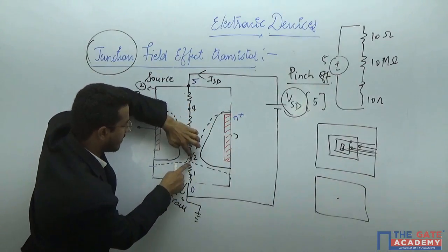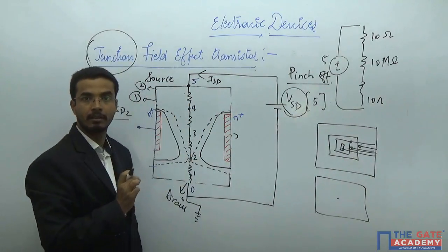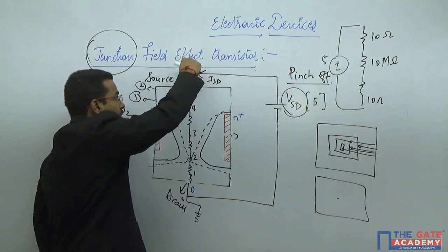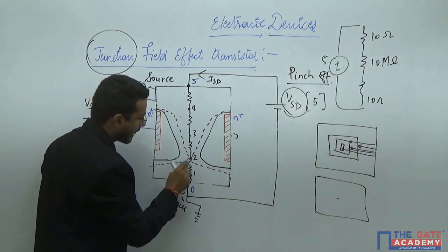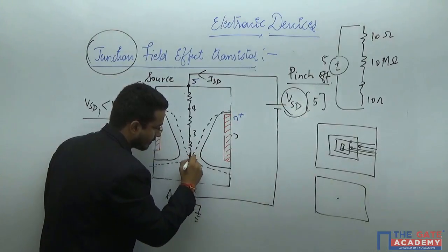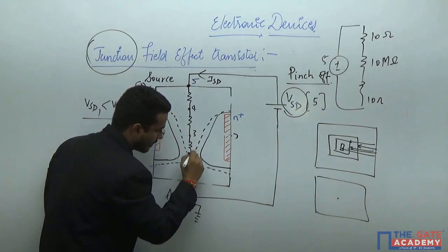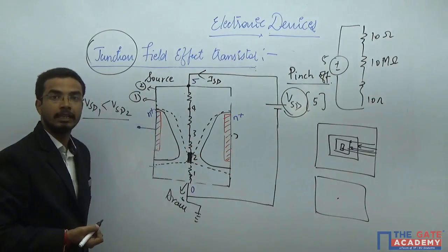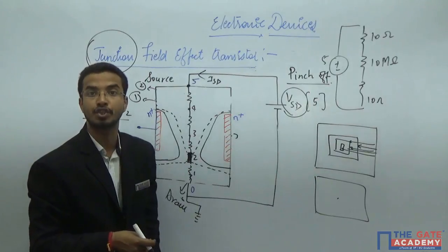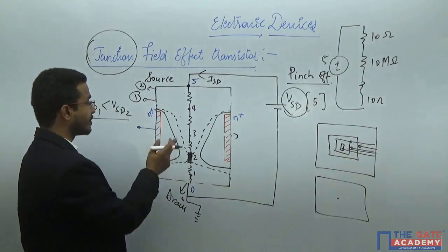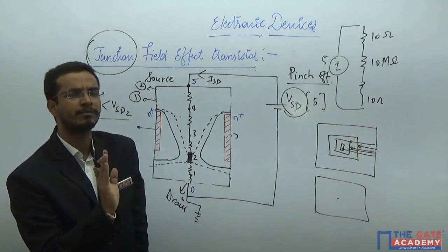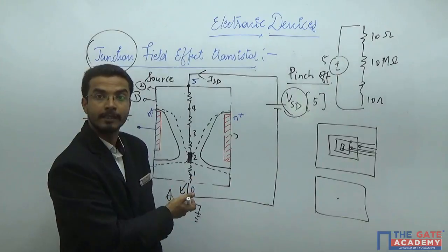And at this time, you do not have any particular channel. Channel means the path for the majority charge carriers to flow from the upper body to the lower body. So at this time, these will touch each other, and this phenomenon of touching, where you do not get the gradual decrement of the voltage throughout the device, is known as the pinch off. And this will be the actual pinch off in the device. Because you have taken practicality into account too, the current will not become zero now, because something else will also happen.